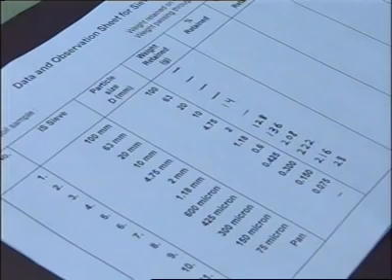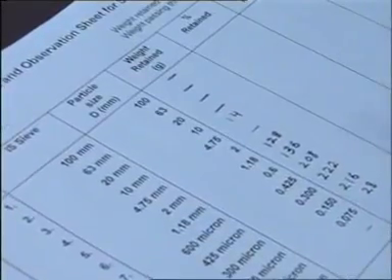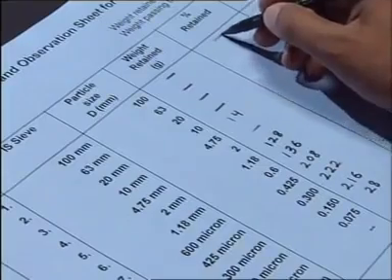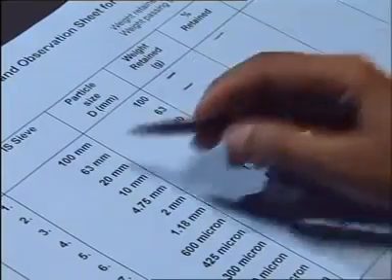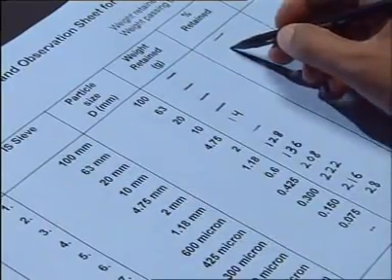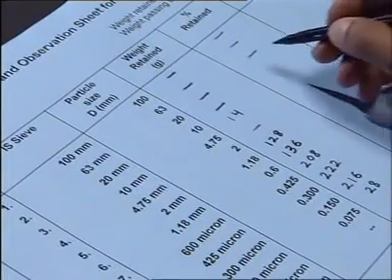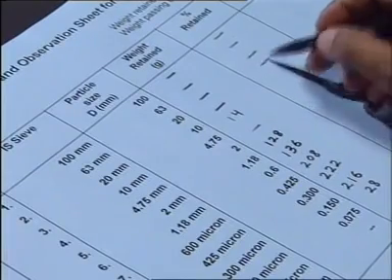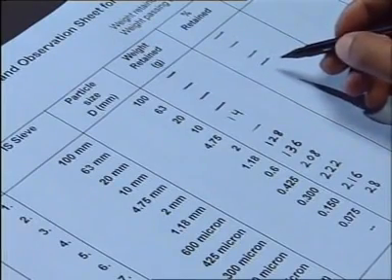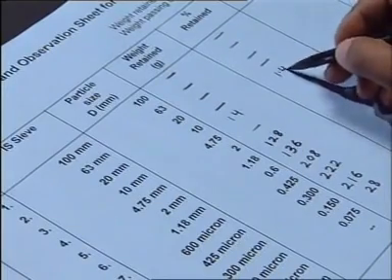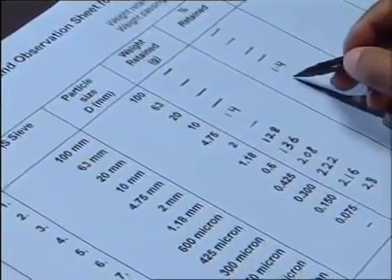After recording the material retained on each sieve, we shall calculate the percentage retained. Percentage retained on 100 mm is 0, 63 mm is 0, 20 mm is 0, 10 mm is 0. In case of 4.75 mm, it is 1.4%. 2 mm is 0,